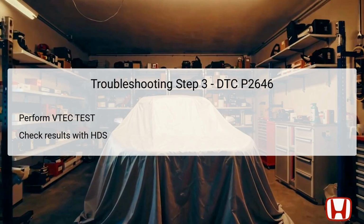After clearing the DTC, it is important to perform the VTEC test available in the HDS inspection menu. This test gauges the functionality of the VTEC system and checks whether or not it operates correctly under controlled conditions. If the results show that the system operates as intended, it may indicate an intermittent failure or temporary glitch, suggesting that the system is functioning normally at the moment.